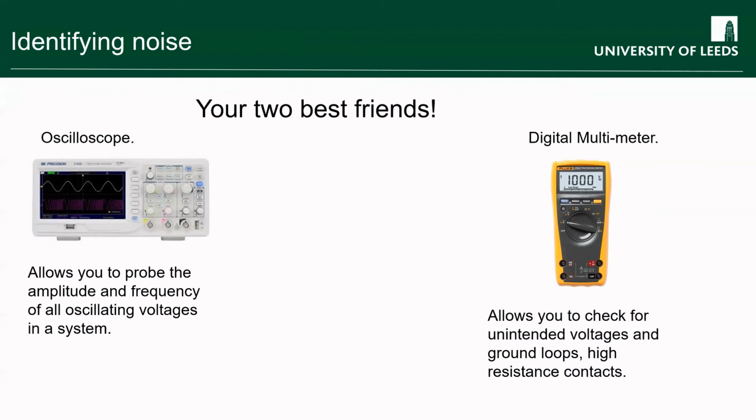And then the other key instrument, of course, is your multimeter, which, if it's a decent multimeter, can not only tell you the voltages, both AC and DC, it might be able to tell you the frequency of the AC voltages, and it will also tell you resistances. Whilst you probably don't want to measure your actual sample with a handheld multimeter, because you don't know how much current it's going to use to do the measurements, if you want to measure your cables to make sure they've got good contacts where you expect them, and that things aren't shorted together when you didn't expect them, then it's an invaluable tool to have to hand.